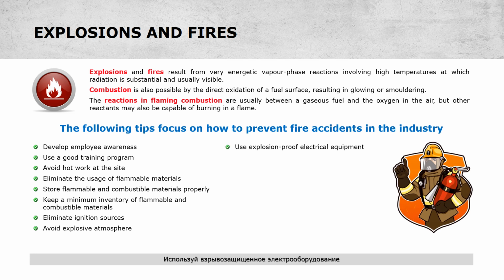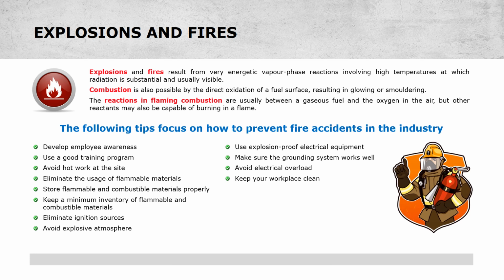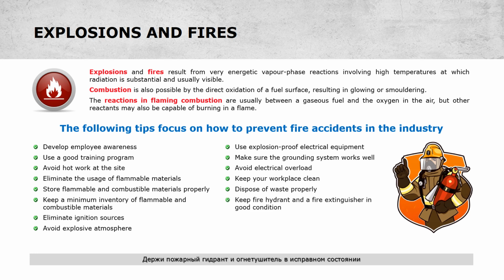Use explosion-proof electrical equipment. Make sure the grounding system works well. Avoid electrical overload. Keep your workplace clean. Dispose of waste properly. Keep fire hydrant and a fire extinguisher in good condition. Perform fire safety patrol daily. Prohibit smoking at the site.